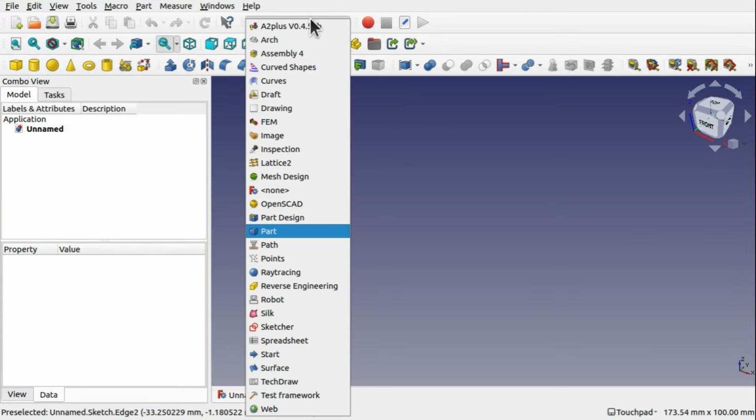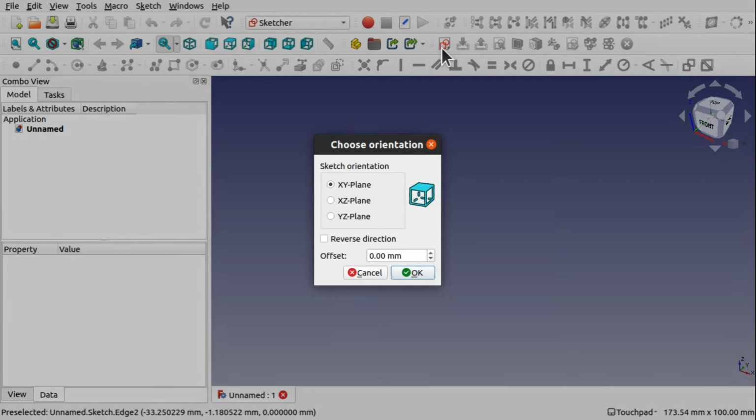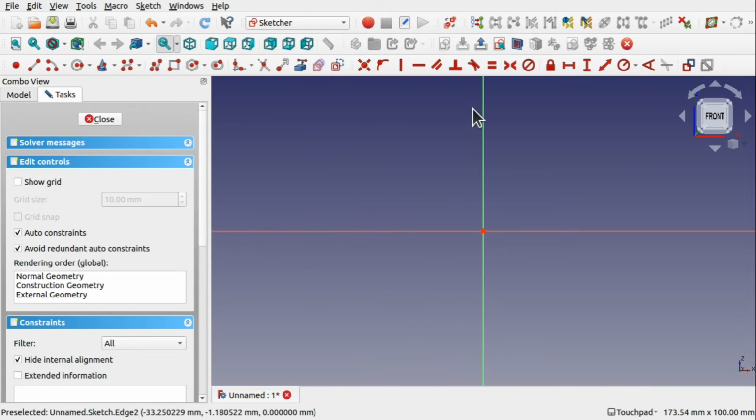And the first thing I'm going to do is come into the sketcher, create a sketch, and I'm going to place it along the ZX plane. So that'll be from the front. So we're looking down here, the ZX plane. And okay that. I was working on the half breadth of the boat, so half the boat. I'm not going to worry about scale or constraints.